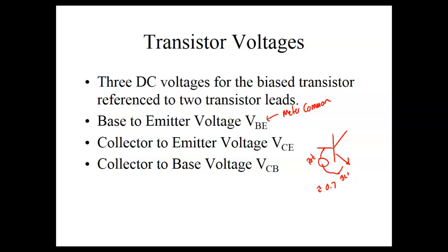It might be 600 when we saturate it. We might have like 1.1 volts there, but 0.7 of a volt is good enough for calculations. And we know now that our calculations are not going to be perfect, but they're going to be close enough so we can understand if the device is good or bad.